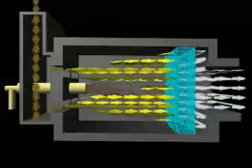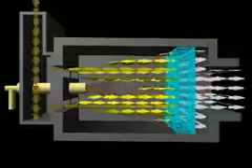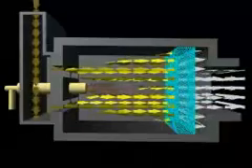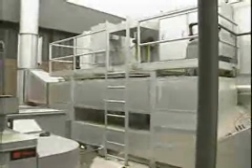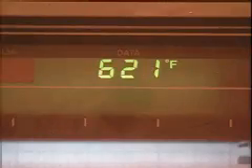In catalytic oxidation, the contaminated gas stream is heated to the required temperature by a gas-fired burner and then passed through the catalyst material referred to as the bed. The catalyst causes the oxidation reaction to occur at much lower temperatures than would be required for thermal oxidation. The typical catalytic oxidizer operates at 600 to 850 degrees Fahrenheit.